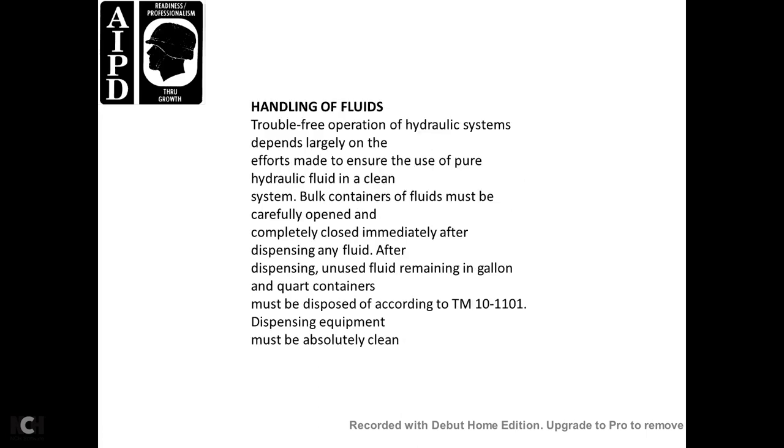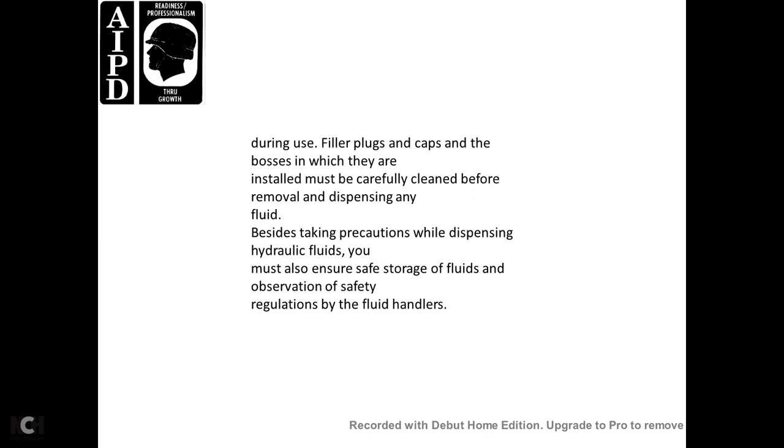Hydraulic fluid handling. Trouble-free operation of the hydraulic system depends largely on the efforts to ensure pure hydraulic fluid and a clean liquid system. The bulk container of the fluid must be carefully opened and completely closed immediately after dispensing any of the fluid. Unused fluid remaining in gallon and quart containers must be disposed of in accordance with TM 10-1101. Dispensing equipment must be absolutely clean. During use, filter plugs and caps of the bosses in which they are installed must be carefully cleaned before removal for dispensing of the fluids.